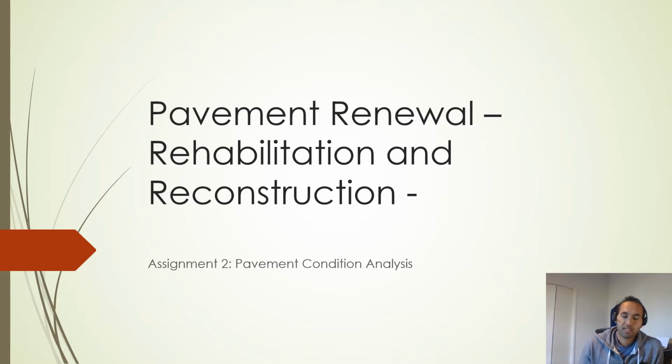Today's presentation is about how we reconstruct or rehabilitate a pavement once we know what the pavement structure is, once we know what the design traffic is, and once we have some falling weight deflectometer data. The options we're going to go through are granular overlays, asphalt overlays when and where they're possible, in situ stabilization methodologies, but also what sort of data we actually need to carry out the overlay design. We'll move on to the next slide.